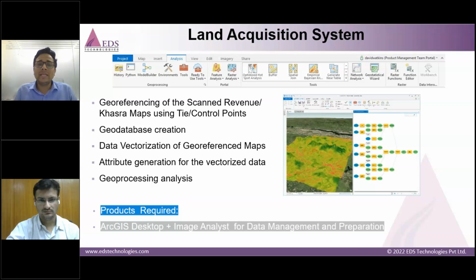So basically you created a drawing file in AutoCAD, and now you want to attach an Excel sheet to it. You can do that. Or if you have khasra plots in an AutoCAD format, you can convert them to GIS format and add this Excel sheet with the data. So that Excel sheet will be attached, and for each khasra, all the information saved in the Excel sheet, you can visualize on a map.